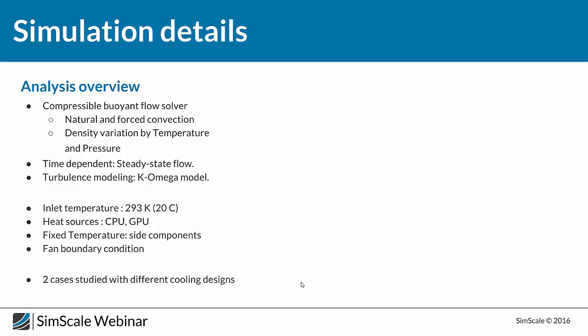And then for turbulence modeling, it is completely a new webinar topic. The topic is so huge, and it has a lot of content to be discussed. So in short, we would be using the K omega SST model for this case, which accounts for turbulence at wall shear stress level.